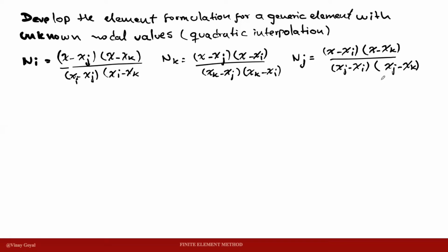So our approximate function, theta, for the transient problem, the time-dependent problem, is also a function of time. So if the shape functions are x-dependent, we want the coefficients or the nodal values to be time-dependent.